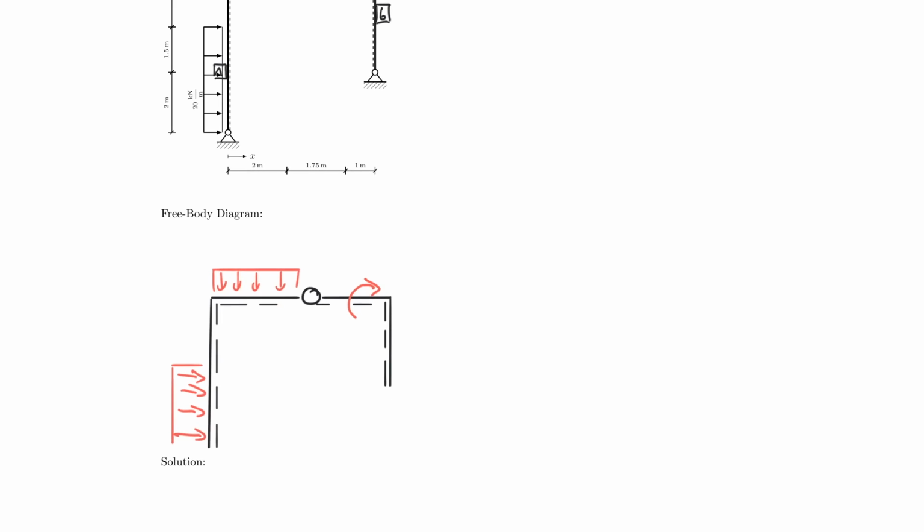And now we can define our support reactions. So I'm going to call this here RAY. I'm going to call this RAX. And it's my convention to always put the forces inside to the frame. And sorry, I confused RAX and RAY here. So let me fix that. Sorry, RBX and RBY. And those are global, right? The X and Y, but we have to deal with the other parts now.